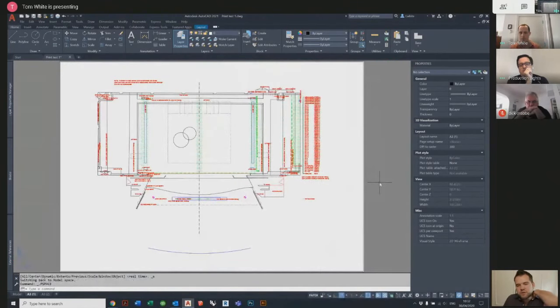And just to jump in there as well, the other command I use quite a lot is zoom to object. So I might, for example, with your 2 circles there, select a couple of objects and then zoom to those and then scale from those. So that's the process to get things to scale to the same size consistently across the different paper spaces you've set up. That's a fantastic way of doing it, and visually it's quite nice, because it means those 2 circles would be centered to the page, so it looks quite nice when it's printed.